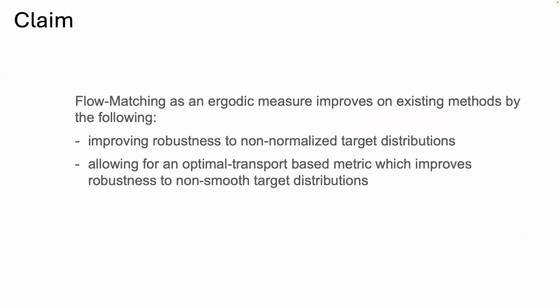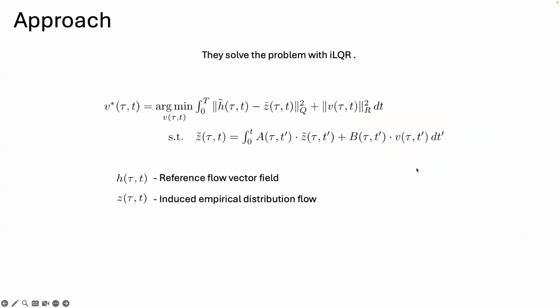Yeah. So the way they handle the feasible constraint space, they iteratively solve the LQR problem, roll it out, get the trajectory, apply it through this flow matching process, and then it shifts towards that direction, and they do this iteratively until convergence.